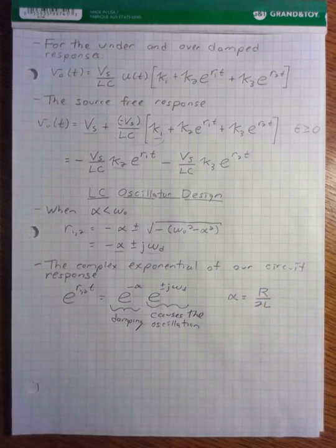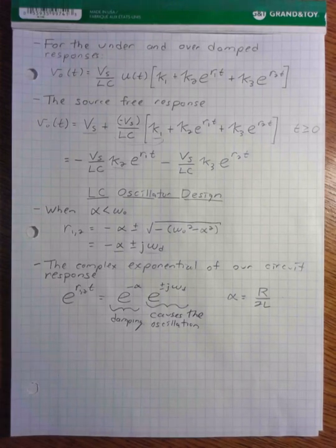And this makes sense because earlier on we were talking about how it's the resistance in the circuit that basically steals energy as current is sort of tossed back and forth between the inductor and the capacitor. And so if we want that exchange of current to keep on going between the L and the C, we would want ideally to remove that resistance so there's no energy being dissipated in the circuit in the form of heat. So we're not going to get a resistance of 0, but let's see how close we can get.